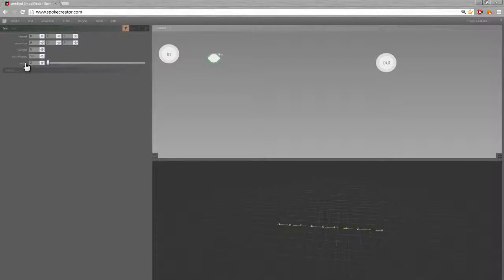And then we've got the order or stiffness of that curve. Now the con of using this way of creating a line is that you're restricted to both creating it from the center and the direction that it goes in. So you can see that if I start to mix up these direction values, we're kind of limited to a 45-degree pattern around the axis. We can still change where the center of that is, and you can use a vector beforehand and plug that into the center option here in the inputs.